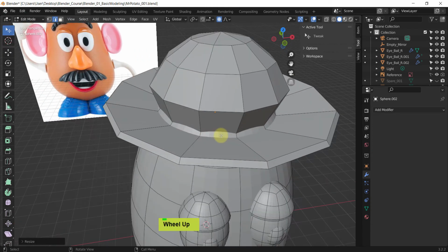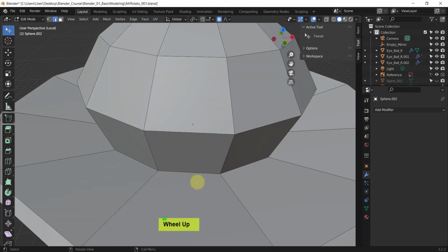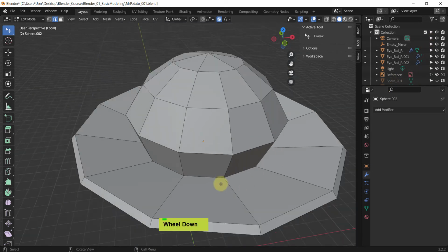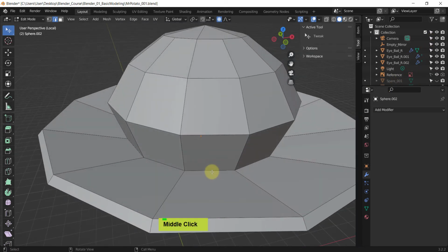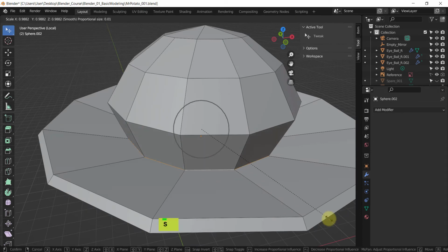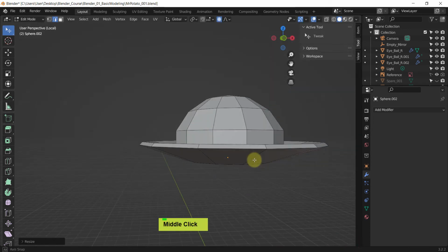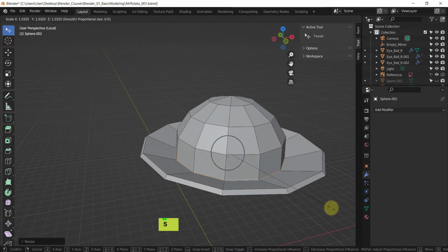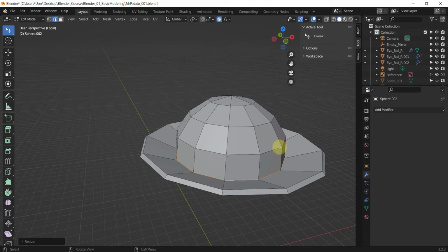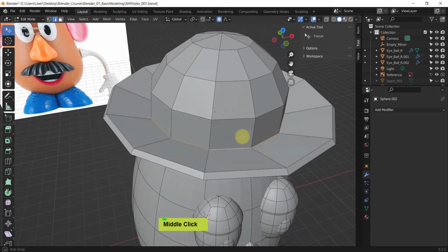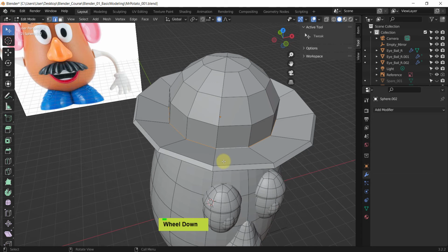Alright, here if we go to isolation mode, that is actually the second button from backspace, isolation mode, or you can use visibility to turn off something if it's in the way, but isolation mode is really a fast way to do it. So I will select edge mode, Alt click in, scale this up a bit, okay, because it was shrinking with my other previous section. And let me leave isolation mode. Okay, that works fine.